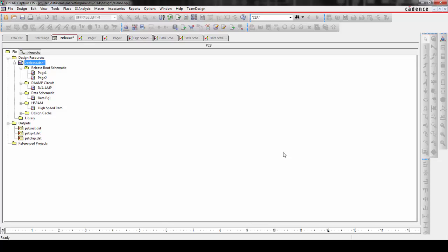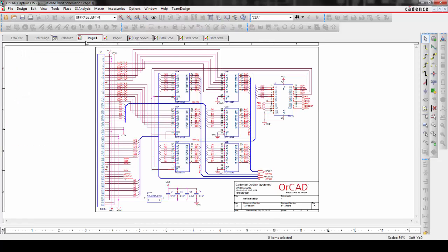The focus of this movie is to show how properties entered in OrCAD Capture may become constraint overrides in PCB Editor. They may also be passed to PCB Editor to assist with placement, to create net classes, and differential pairs. We will start by assigning component properties.